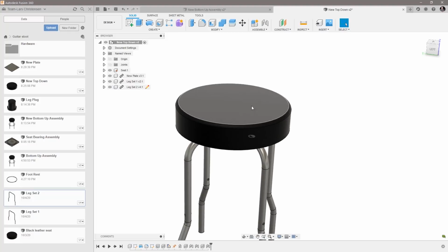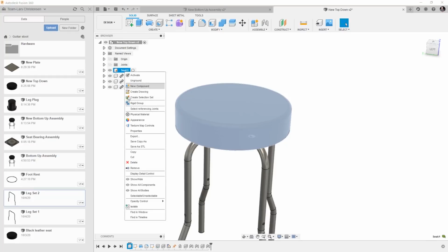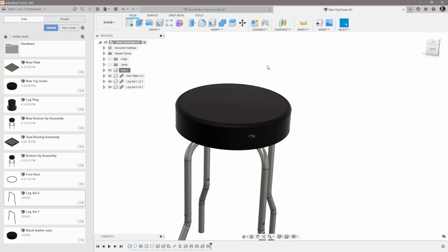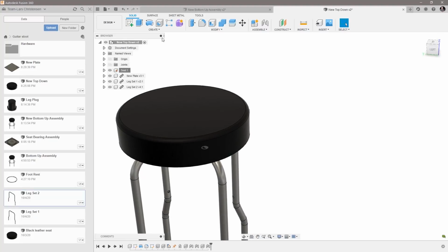And that is great when you model one thing up, like the seat, for example, and you now want to make a new version of the seat. You could do a save as. That's what most people would do. Click here and do a save copy as. But if you want to keep this as our basic seat, and create a new version of this, but any changes we're making to the original go to the new model, but not backwards, we can use Derive. So let me just show you how that Derive works.